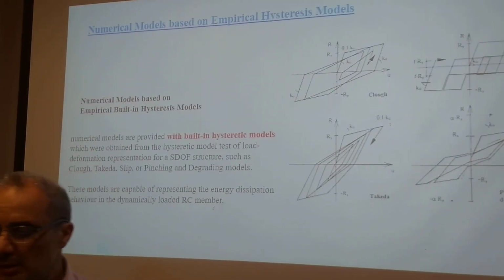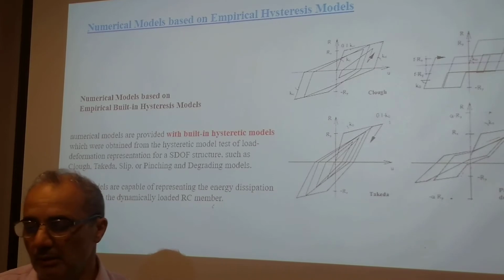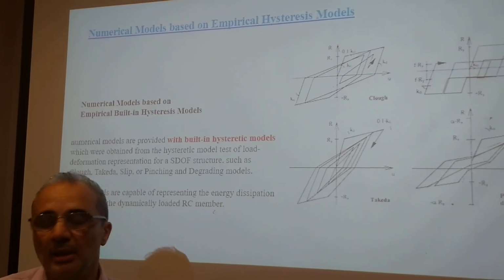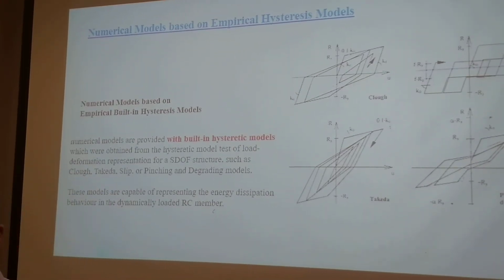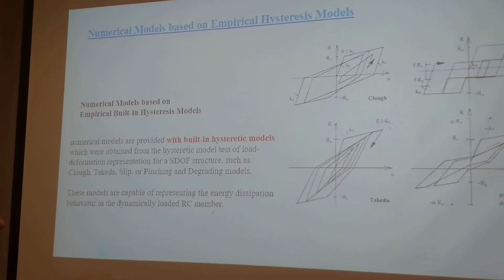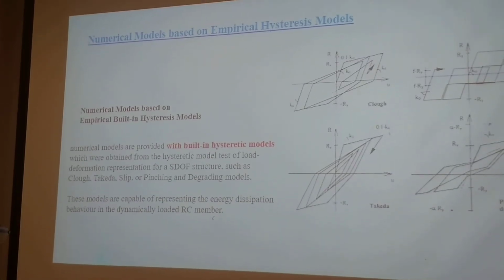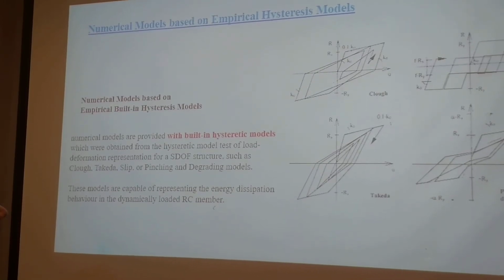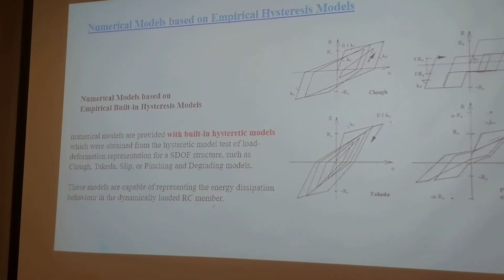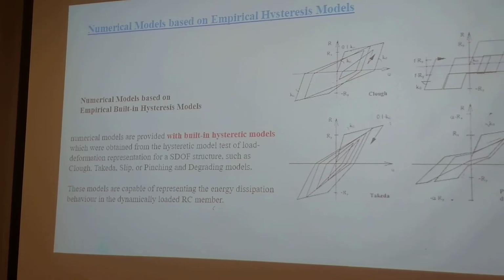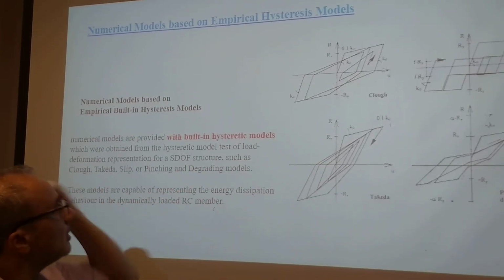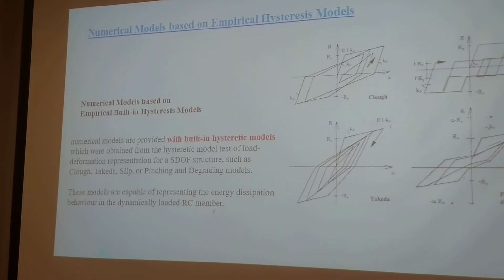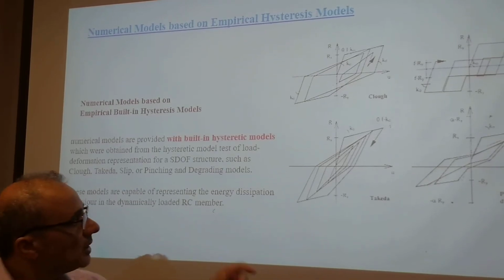Other numerical models are based on hysteresis models. It's a hysteresis model that is built within the code itself, and we can choose the ones that are more suitable to our problem, such as the Clough hysteresis model, the slip model, the Takeda model, and others.